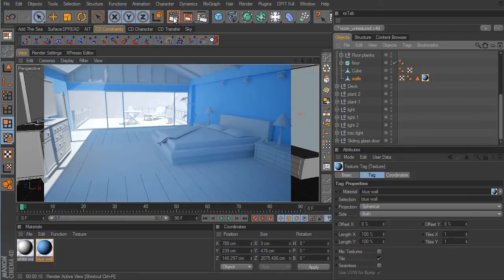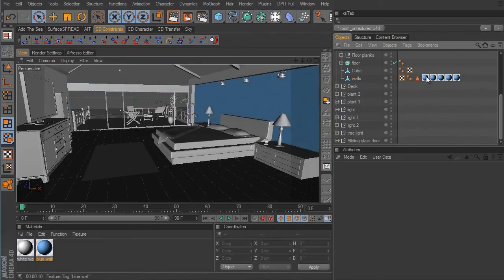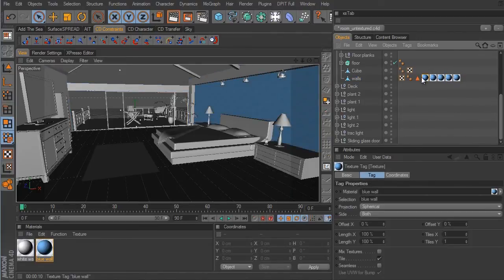So the only way to work around this is that you have to set your materials up in layers. The object manager over here works from top to bottom, and then for the material over here it works from left to right. So let's just say that we have a bunch of materials here, and I'm just going to duplicate this a couple times. This material here on the very left would be the very base material. It would be the material that is sitting on the bottom.